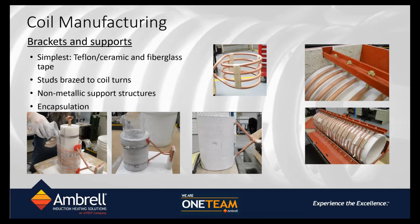But as you can see from the pictures at the bottom, it's a pretty involved process to encapsulate a coil. And this coil is just a simple circular design. If you had an elaborate big coil, the encapsulation becomes heavy and pretty unmanageable. So studs are incorporated with ceramic insulation in a lot of cases, and that choice has to be made whether it's a good fit or a bad fit for encapsulation.